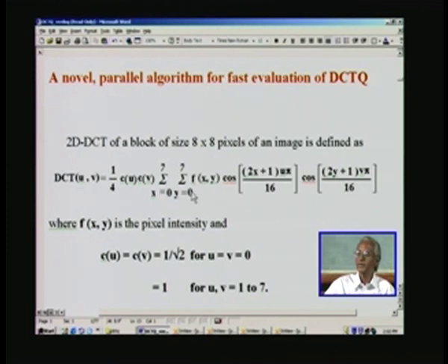The average would be a division by 64, whereas we deal with only 8 here. So it means 8 times the average information is contained in just one coefficient. In other words, if you take just the DC coefficient alone, code it, transmit it, receive it at the other end and do the inverse operation, you will still recover the whole image. Only details may not be that easy to see, and you need much higher coefficients in order to create the detail, especially at the sides, be it vertical or horizontal or even diagonal and so on.